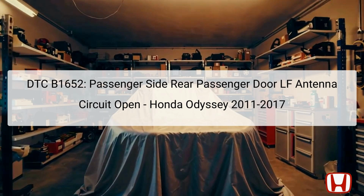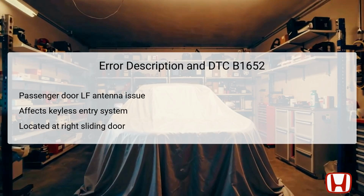The malfunction can lead to inconvenience as keyless access may become unresponsive. If diagnosing, it is essential to consider that this type of issue may stem from wiring problems or component failures. Proper diagnosis using the Honda Diagnostic System, HDS, is integral to pinpointing the exact cause of the fault to allow for effective repairs. The DTC B1652 specifically indicates an issue with the LF antenna circuit located in the passenger side